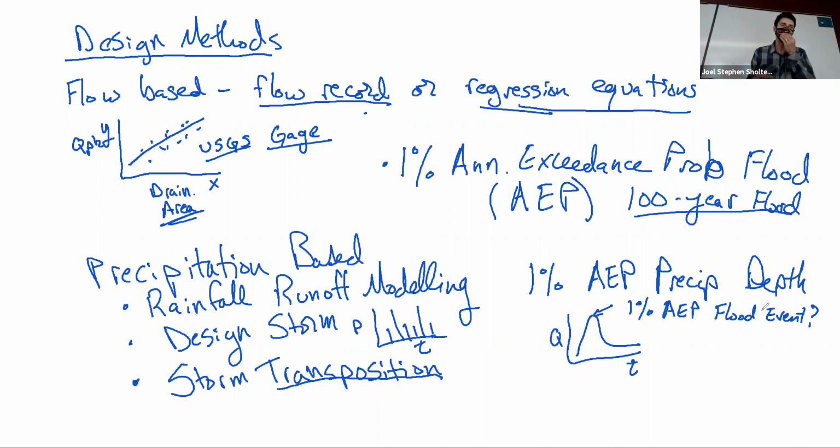However, when we do rainfall-runoff modeling, we often make this assumption, and we can make some conservative assumptions to ask what the worst-case scenario runoff event would be if we got this precipitation event. So say, for example, the watershed was already soaked with water and the soil is saturated.